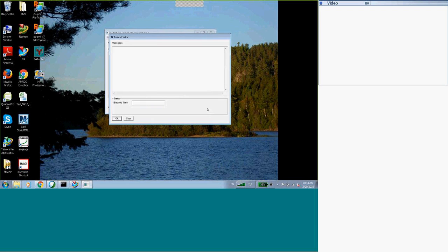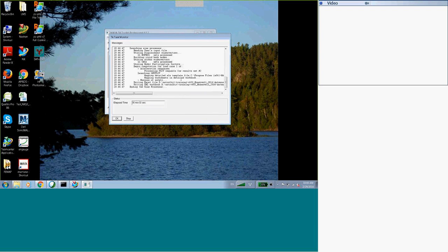And let's click OK, and let's start this. You notice 16 sets being processed. My first resonance is at 70 hertz. I'm exciting up to 50 hertz, but it's not all the modes. So those serial vectors are being excited.